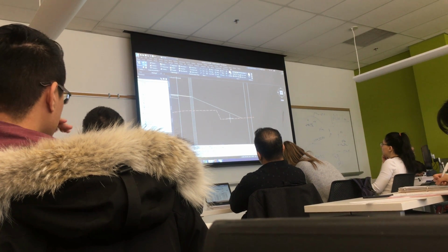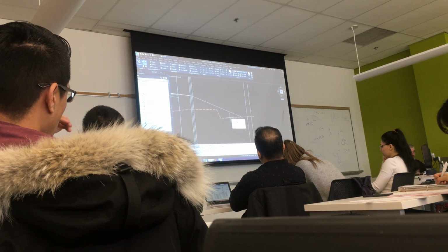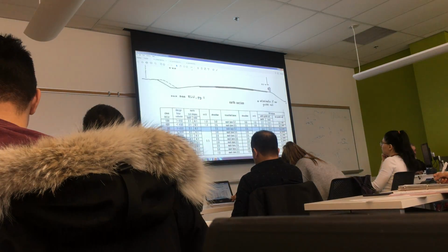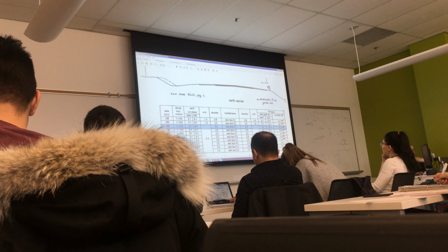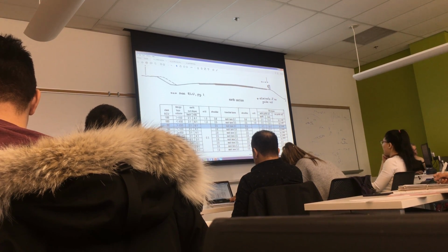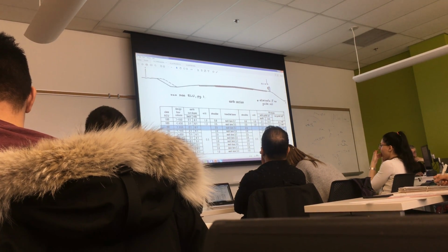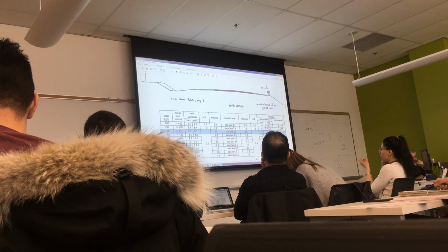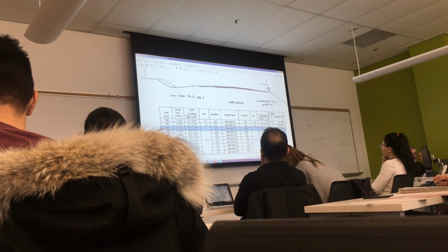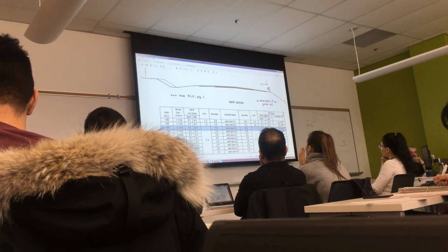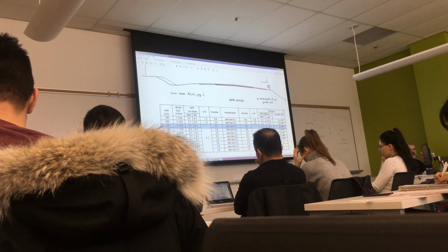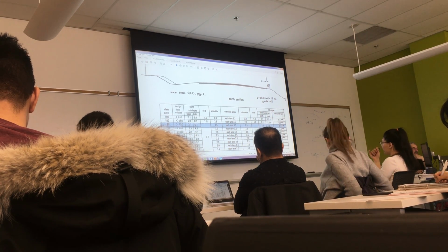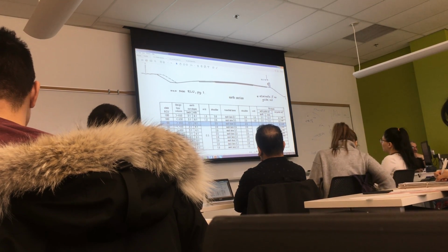If I use 3 to 1, I might need a guide rail. I might not. I don't know, right? If you go back to the design requirements, if you have no guide rail, you must use 6 to 1. If you're going steeper than 6 to 1, and I'm using 3 to 1, I might need a guide rail. I'd have to analyze this. Okay. For now, just draw it without the guide rail. We'll analyze it later. Probably not today, maybe later this week. It might not come into play on your side. The other side, again, 6 to 1 on both sides without a guide rail.